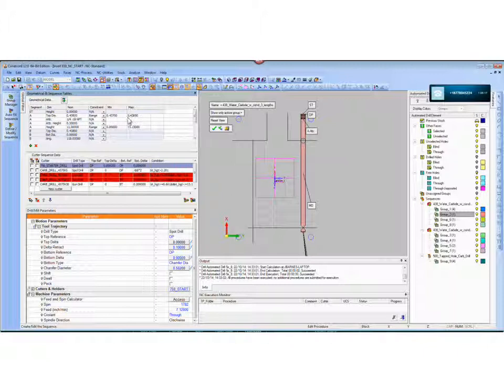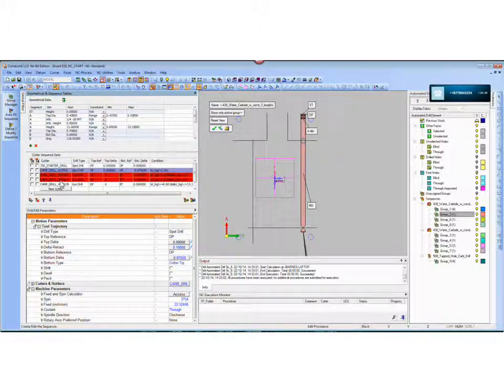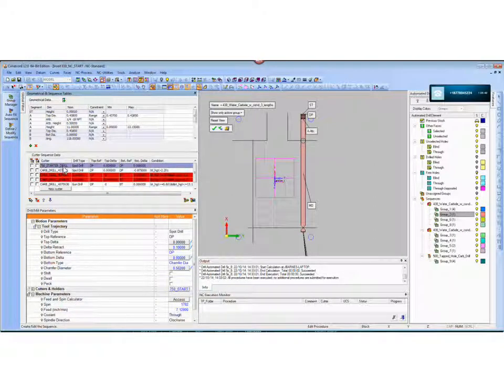Here's the depth from 8.50 to 13.15. Now 13.15 just happens to be the full depth that I can drill with my 30 length ratio drill. Anything more than that, and the 30 length isn't going to do it. So I went ahead and minimized that range. Now down here, these colors mean something. Actually, purple here is just a highlight, so don't worry about that color. But the red means that this one's not being used.